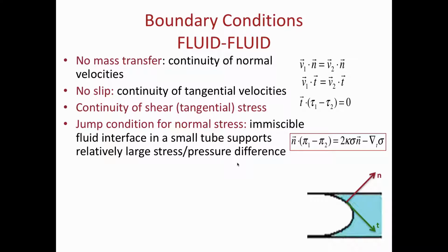We're not going to be dealing with it most of the time, but just understand that if I have two fluids, I don't necessarily have continuity of the molecular stress. I might have a jump. Okay? So different stresses in one fluid versus the other. Most of the time, our boundary conditions apply continuity of something or other. But in this case, I could actually have a jump, specifically because thermodynamic stresses in two different fluids with two different molecules can be different.